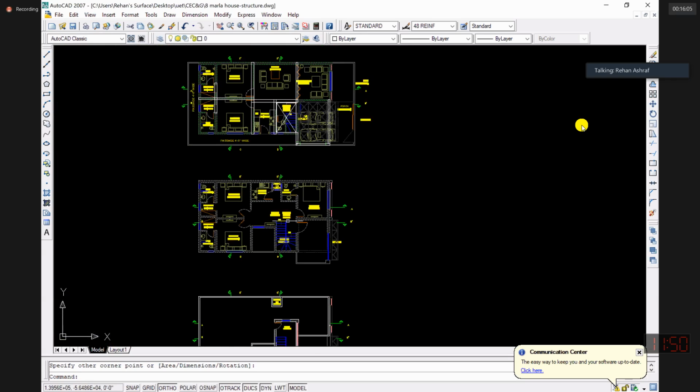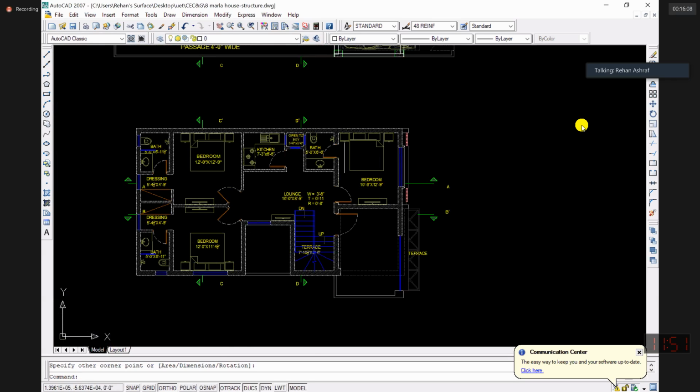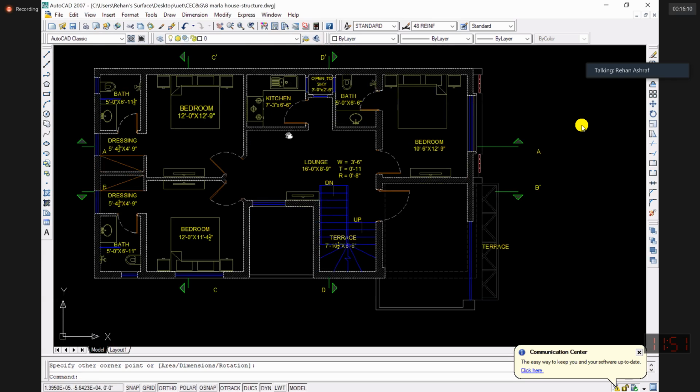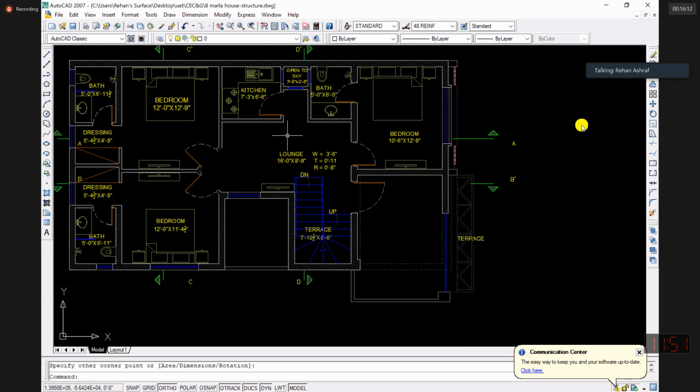Similarly, you would do the framing of the first floor. In the first floor, if you have a roof over the first floor, what do we have to see? At this very basic level, you can only consider that if you are having 4.5 inches wide walls, do not put load over a 4.5 inches wide wall. So that is the minimum that you can do at this initial level.